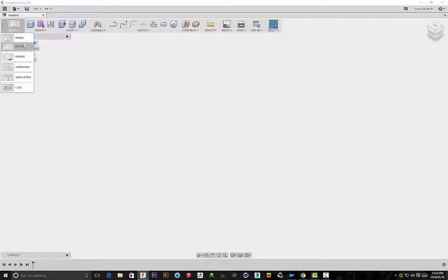So you'll see there under workspace, it's called patch. Now I'm not 100% sure what this particular workspace is used for, but I know I use it for one thing and one thing only, and it's that technique that I'm about to demonstrate to you. So we'll head into that workspace in a moment. But before we go there, in our model workspace, I'm just going to create a basic sketch, right? We're going to be drawing this sketch in the model workspace, and then we'll be drawing that sketch in patch. But I'm going to be showing you that when you use patch to create the sketch, you'll need to use a lot less steps to create this piece of geometry.